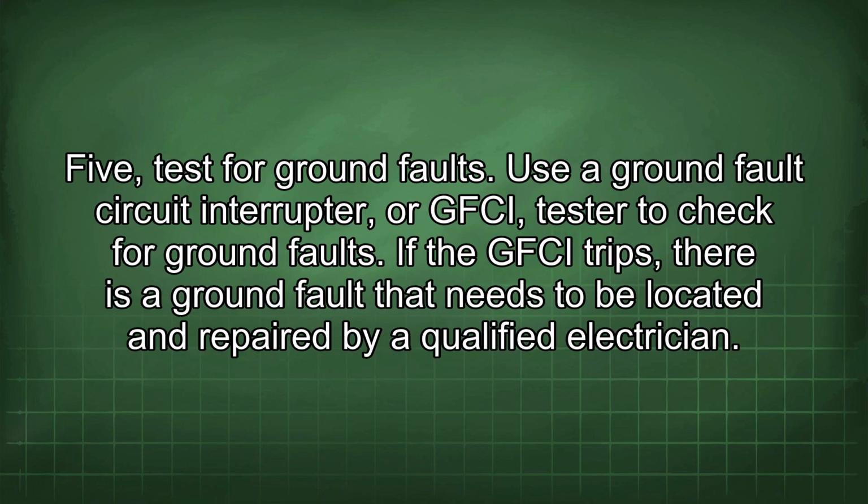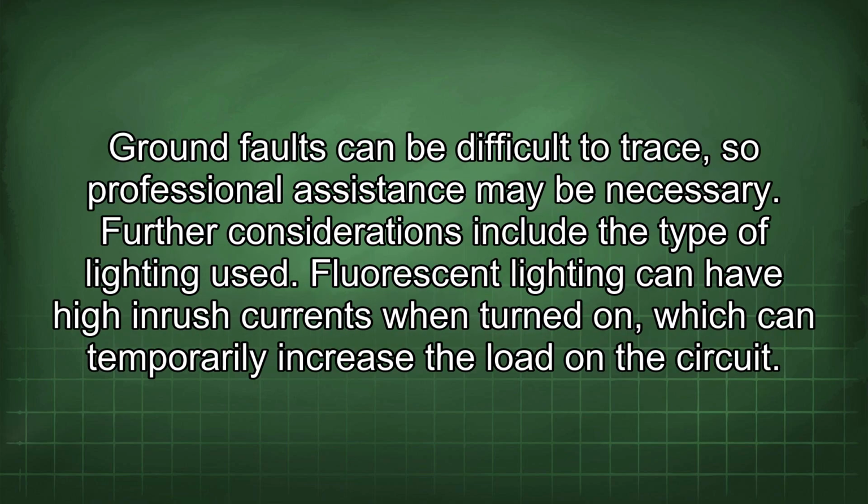5. Test for ground faults. Use a ground fault circuit interrupter, or GFCI, tester to check for ground faults. If the GFCI trips, there is a ground fault that needs to be located and repaired by a qualified electrician. Ground faults can be difficult to trace, so professional assistance may be necessary.